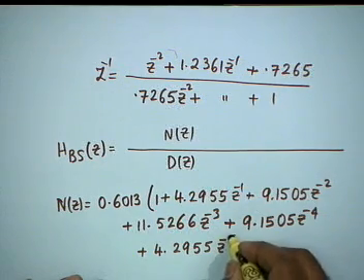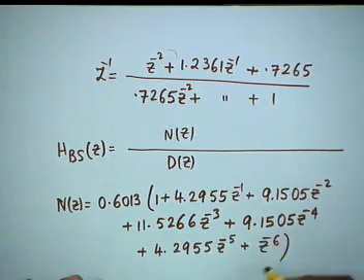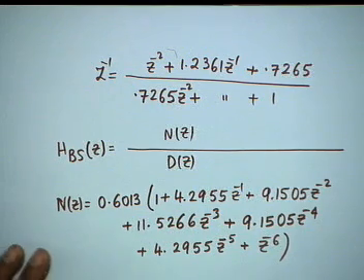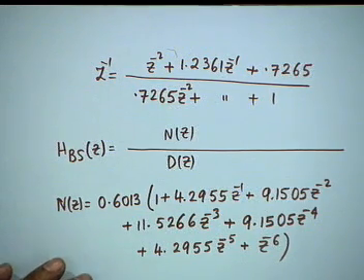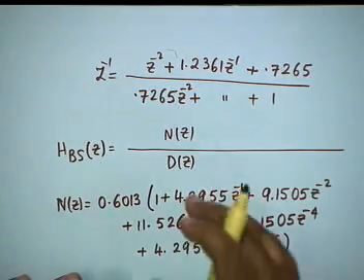Do you notice something interesting? Symmetrical, linear phase. The numerator is linear phase, not the total filter, because the phase is affected by the denominator as well. Why did it come like this? Once again, it is also a reflection of the fact that the transformation is all pass.